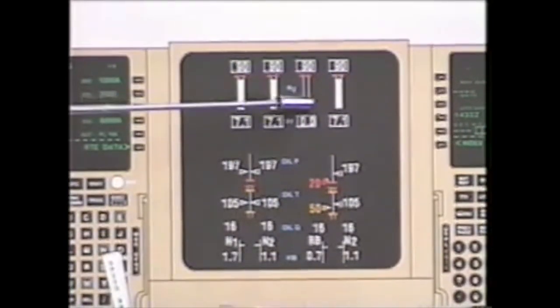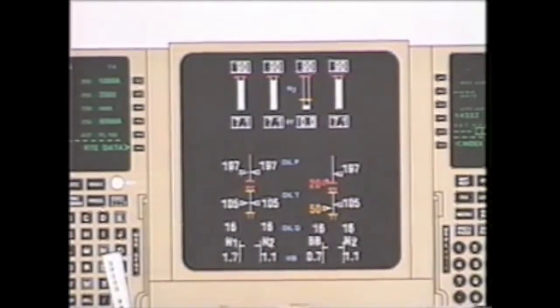This line on number 3 engine, which is shut down, indicates the minimum fuel on line, which would disappear after the first officer brings the fuel lever up to run. Oil quantity, the minimum oil quantity for engine start is 18 quarts. Other synoptics again available would be fuel, hydraulics, ECS, gear, so forth.